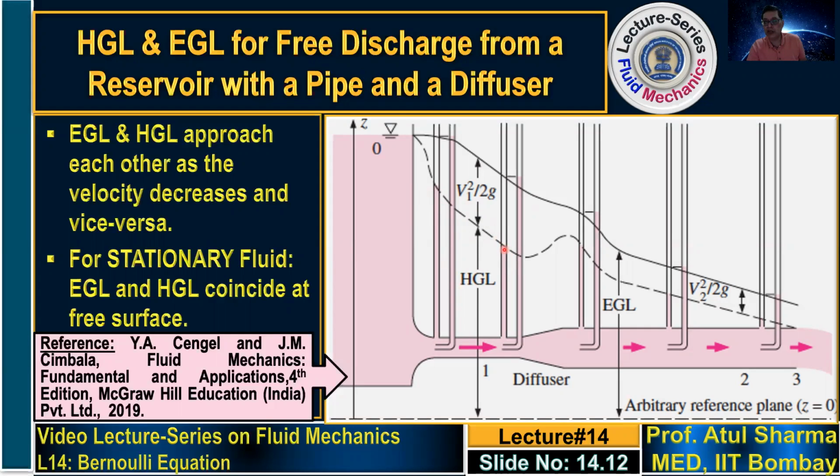Similarly, when you consider the larger pipe diameter, if you consider three locations, let us say this location as x1, this as x2, this as x3, and the static pressures as P1, P2, and P3, then the pressure that you measure, P1, is greater than P2, which is greater than P3. So in the practical situation, the static pressure is reducing.